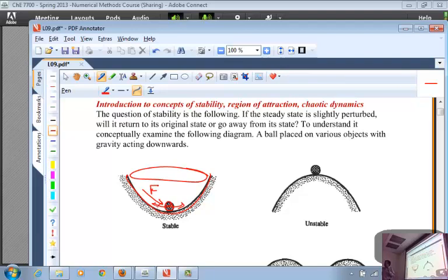No, damping. So what causes it to lose the energy and come to a rest is a dissipation mechanism, friction, for example. Friction with the solid or drag with the air. Both are dissipative mechanisms. If you didn't have them, if you did it perfectly in a vacuum on a perfectly smooth surface, there is no friction, then it should go forever. Why? Because as it goes up, the kinetic energy is converted into potential energy, then it comes back, and the energy is not dissipated, it is conserved. Okay? Now that's a stable system.